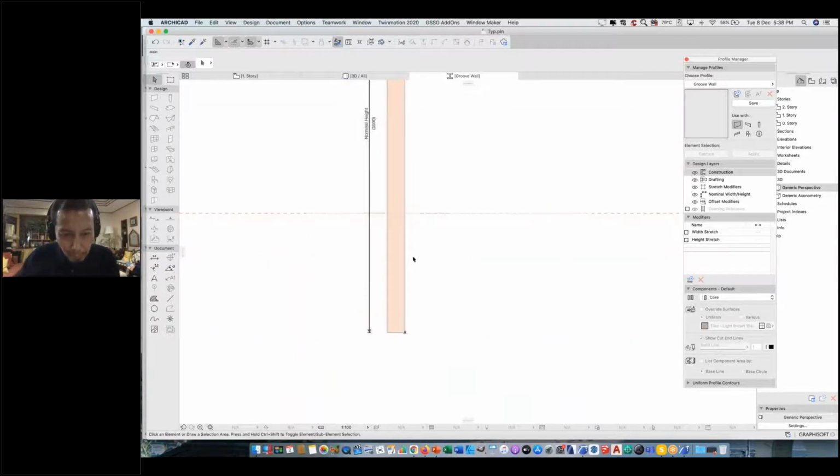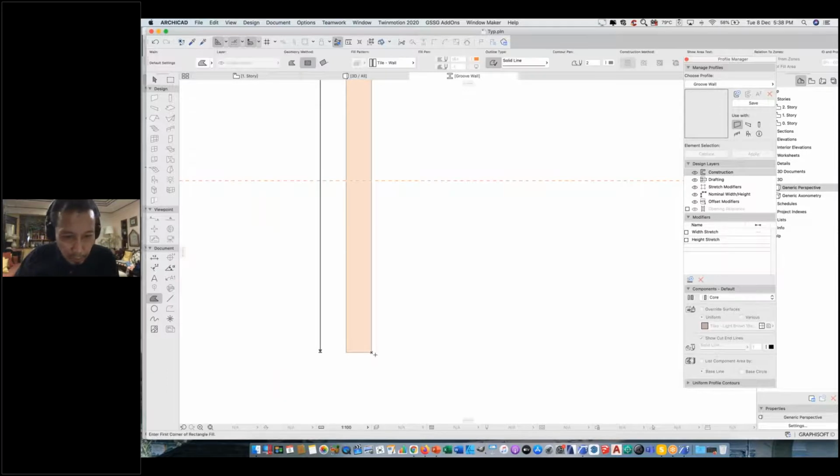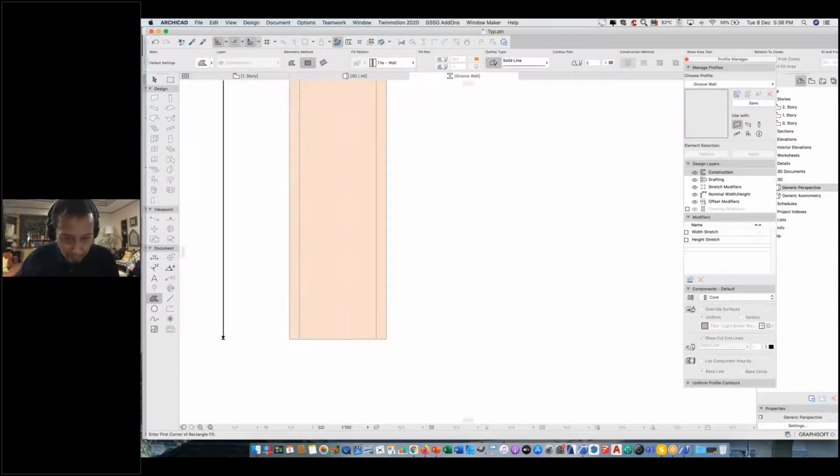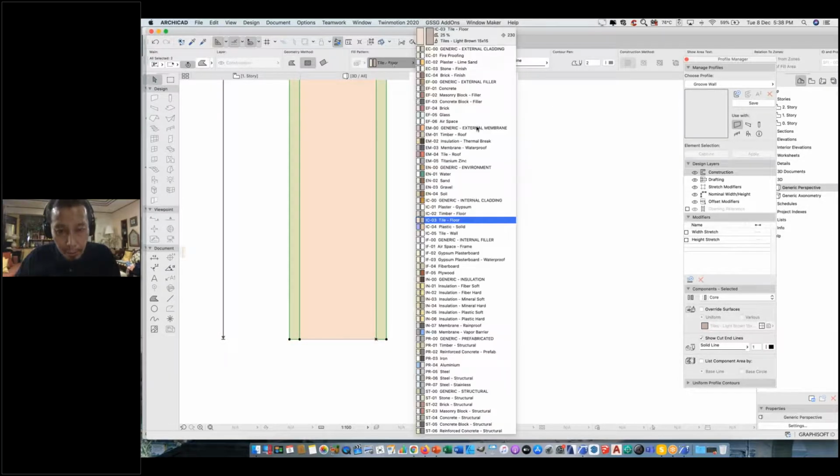And I'm going to make another profile, maybe 20 by 3500. I'm going to make this a plaster. Same as here, maybe 20 by 3500, and I set this part as the origin. So this wall here, I'm going to make as plaster gypsum.